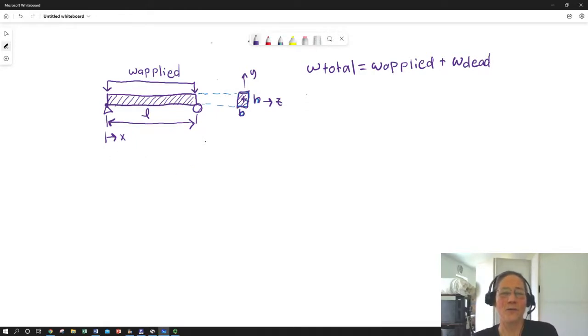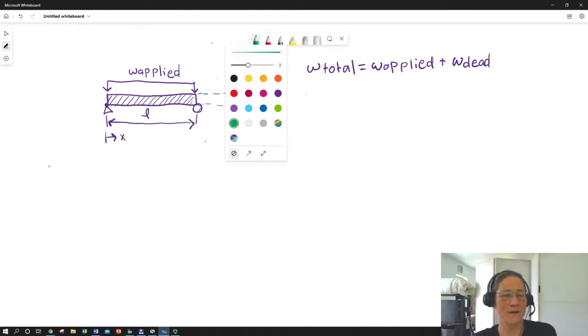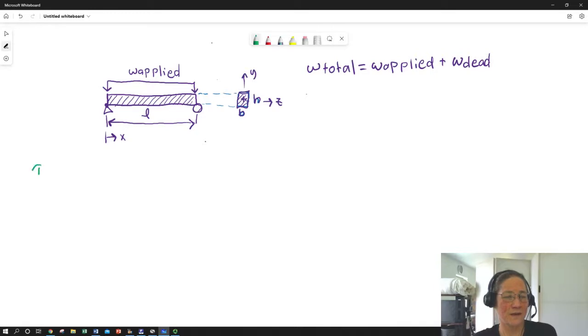So we're going to make a list now of the things that we would need to know for design. So we can start with number 1. And again, these are things that we'll of course want to compare to material properties. We're going to want to know specific weight. We'll start with our material properties, because we need that to calculate our dead load, which, depending on what applied load we have, could be a significant part of the overall uniform distributed load.